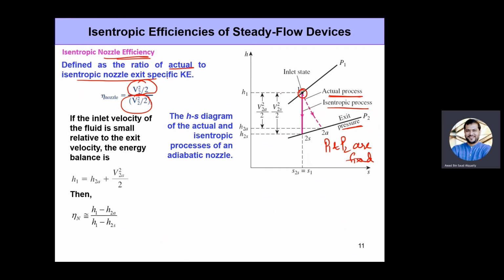We're simply saying that you have a nozzle. The role of a nozzle is to increase the velocity. We have V1 and V2. We know that the whole purpose why we build a nozzle is because we want V2 to be greater than V1, in fact, much greater than V1. And we are able to achieve this by decreasing the pressure. Okay, P2 is smaller than P1. Now, the point is V1 is usually really, really small. Okay, so we only focus on V2 because that's our target.